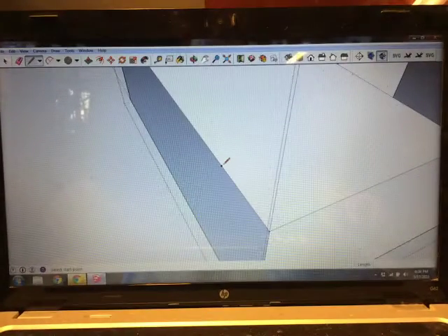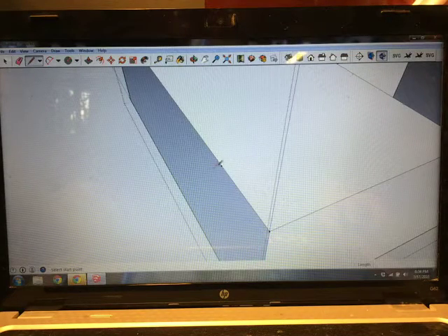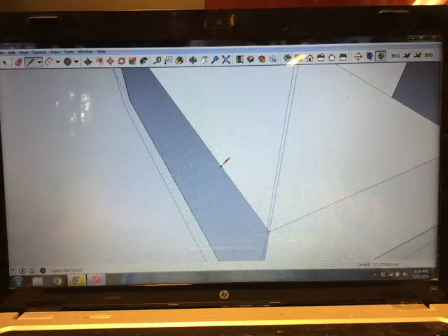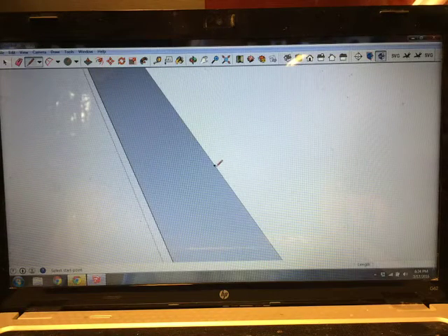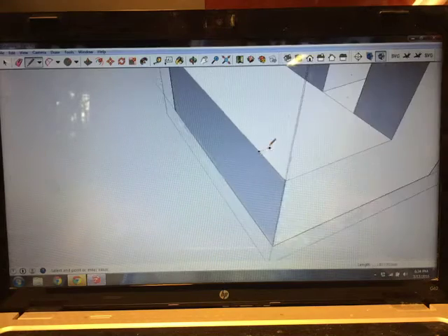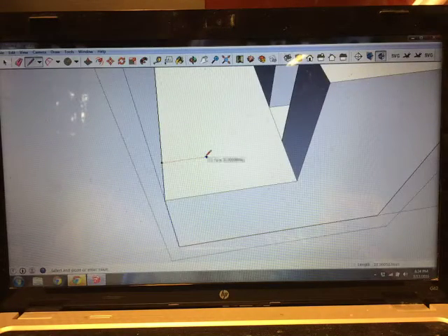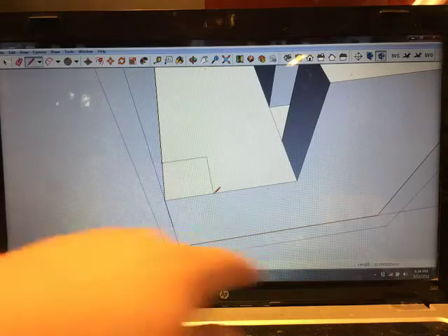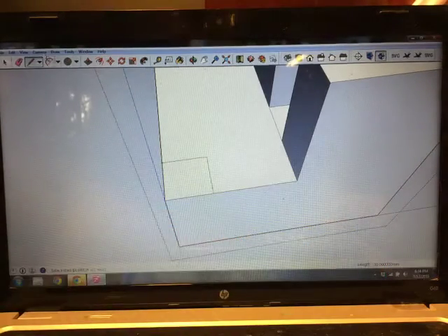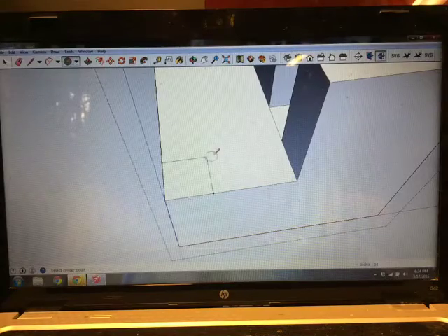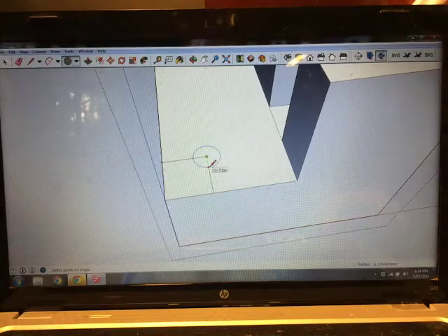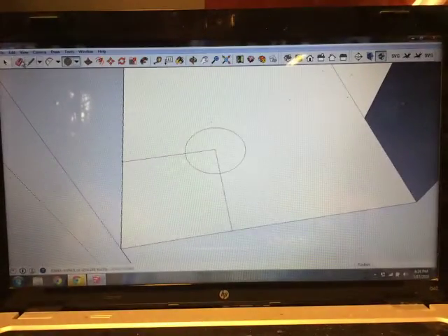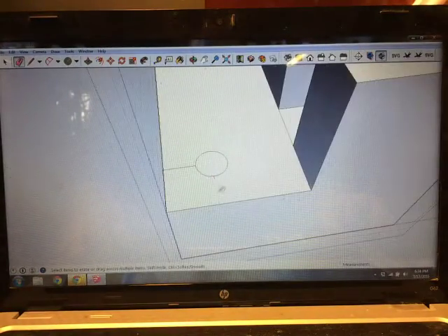Well, you can make sure when you click that the guide point is selected. But you can work off that guide point 30 millimeters, 30 millimeters, and you can double check your lengths down here. And then let's say that's the center where the hole needs to be, and your hole has a 10 millimeter radius. Then, I mean, that's how you do it.